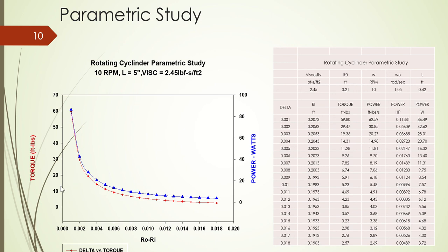So our torque increases, and also the power necessary to turn my motor also increases as well. So it's good to understand the torque and the power, because ultimately, as mechanical engineers, we have to size the motor necessary to turn the shaft, to turn the cylinder in the gap, and the power influences the size of my battery pack, and the current draw from my battery pack as well.